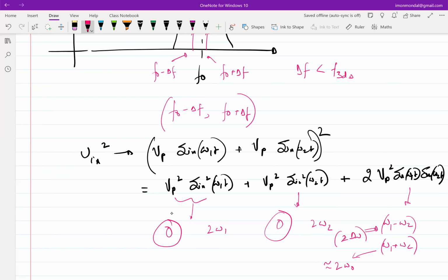You set it as some DC bias, and you apply a sinusoidal input. But because of the distortion, you will see that at the output side of the amplifier, the DC bias that you intended to set has deviated. And that deviation can be quite large, given that this VP may not be in your control at times. Okay, so that can be an issue.